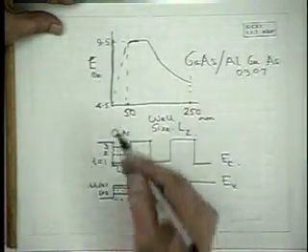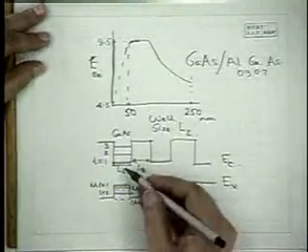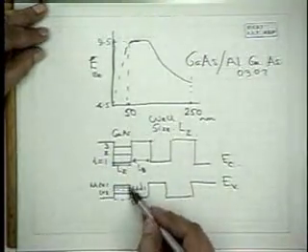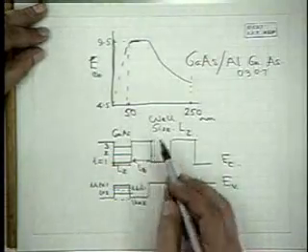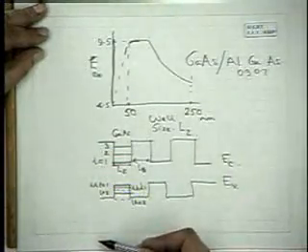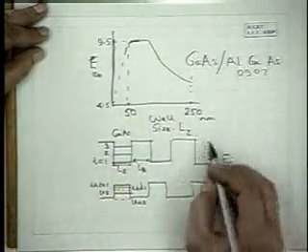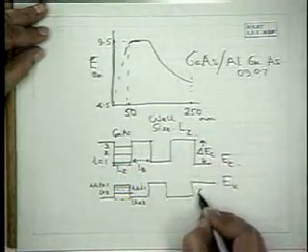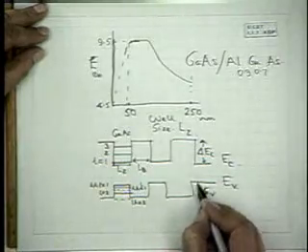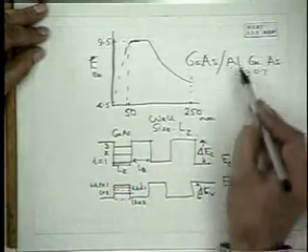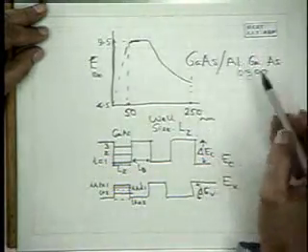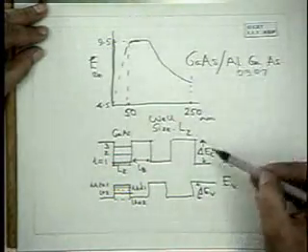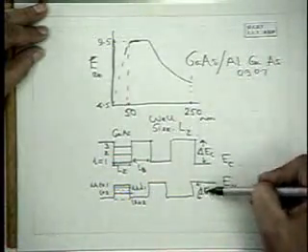So we have a series of ladders corresponding to light holes and heavy holes in the valence band and electrons in the conduction band. And this is the conduction band discontinuity, and this is the valence band discontinuity. These depend upon the aluminium composition. As the aluminium composition increases, these delta EC's and EV's increase.